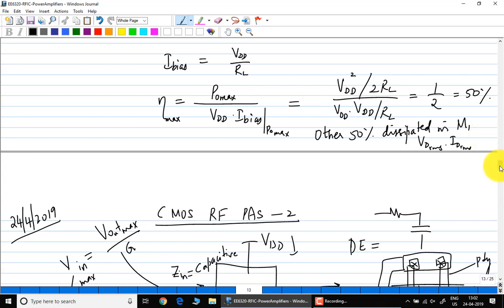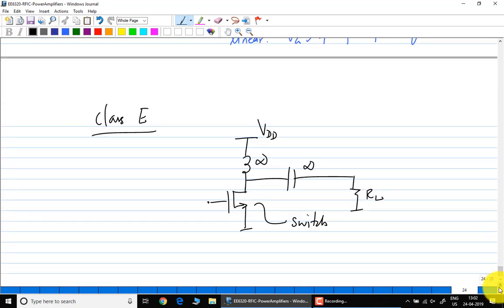Now, I'm going to take this and make the MOSFET like a switch, right? Because the input is biased at VT. When it's positive, it's high, otherwise low. Now, imagine I removed the MOSFET and had an ideal switch. What is the power dissipated in an ideal switch? It's 0, because when it is on, the voltage across it is 0, even though it can conduct a lot of current. When it is off, it has a lot of voltage but 0 current.